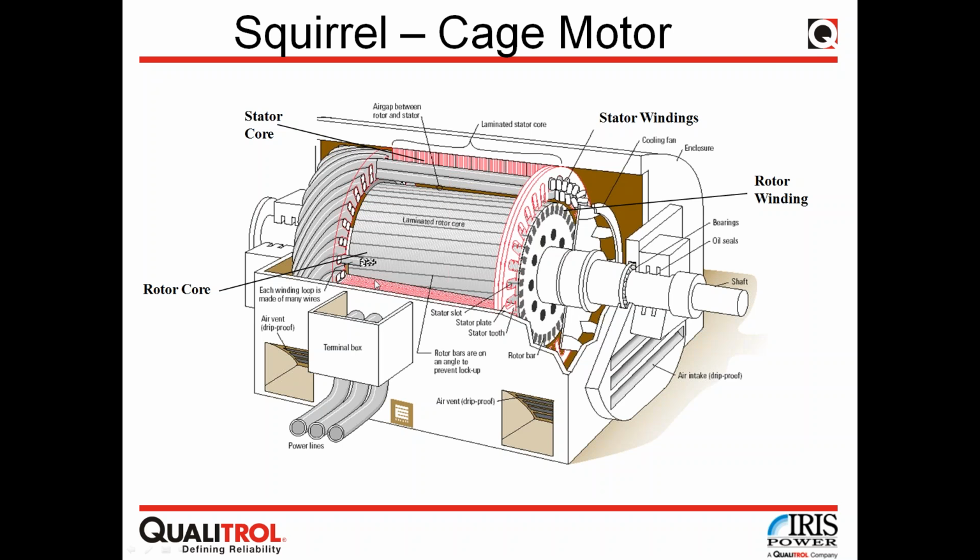That rotor is in the center of the picture, and it is based on a laminated rotor core. What does it mean? It means that the rotor is made in a similar manner to a stator. There will be a number of laminated sheets held together, and there will be conductors inside of that sheet, which will be basically some sort of bars, most frequently aluminum bars, and those bars will be connected on each end of the rotor, forming the so-called squirrel cage rotor design.